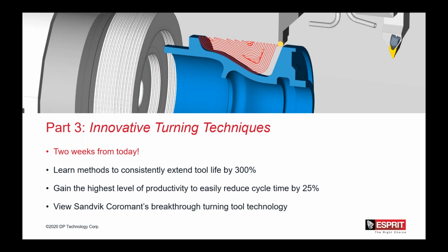No, there's no need to on breakthrough to drop the pressure. The only time is if sometimes you hit an intersecting hole and you don't drop the pressure, but you change your feed rate as you go across. So if you're drilling in one side and then you're hitting a hole in the middle and going back into the other side, you're going to drop your feed rate across that hole and into the other side and then bring it back up. But coolant pressure can stay at 100%.